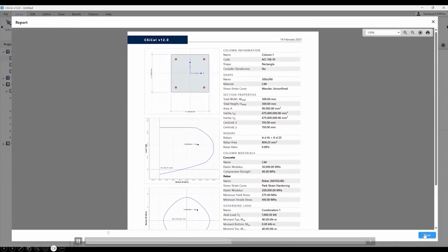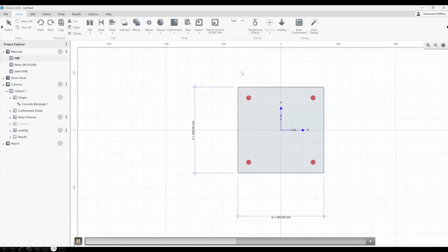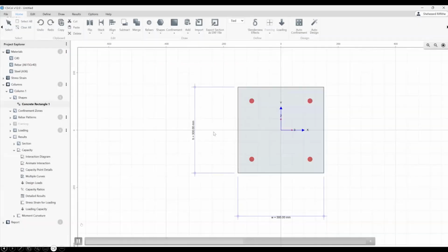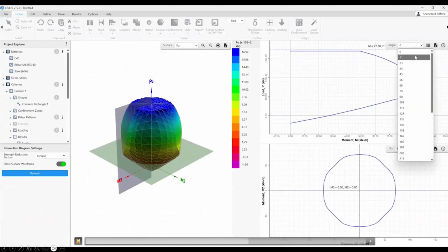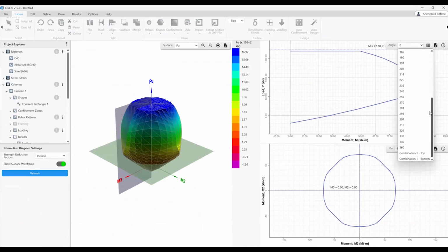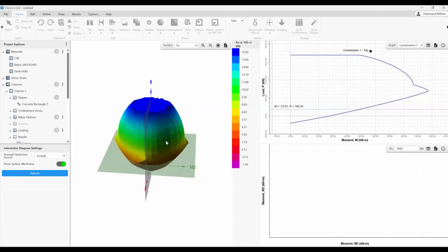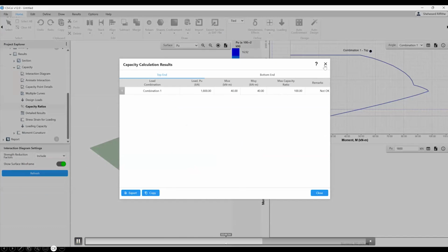Now let's move to another step and assume that we are increasing the loading for this section from 1000 to 1800. When this loading is increased, we will have our capacity outside of the interaction surface, as shown here in the interaction diagram. Now, in a case like this, what can be done? Let's look at that next. As you can see here, the remarks say it's not okay.